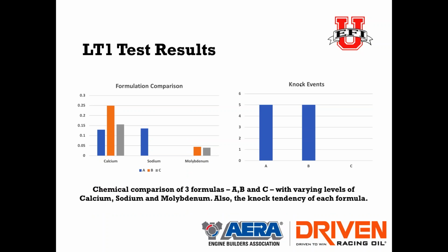What we found validated the earlier work, where it seemed like the calcium and sodium are bad actors, and the ZDP and the moly are good actors. We looked at 3 different base formulations. Oil A is a mixture of calcium and sodium detergents, and running that oil in that engine test series, it produced 5 knock events.